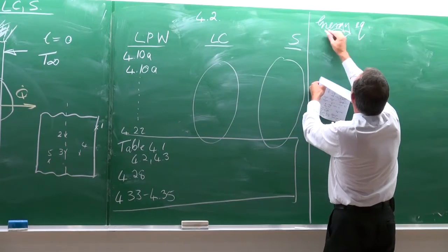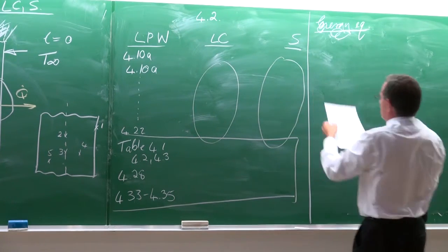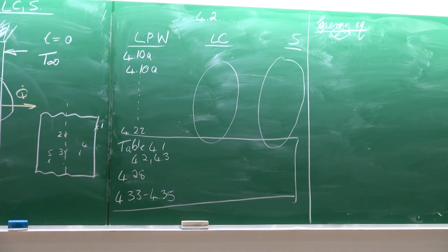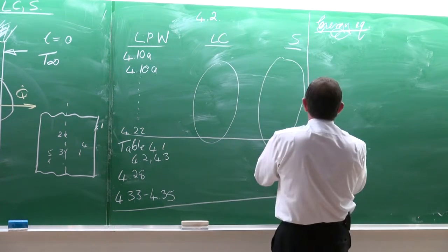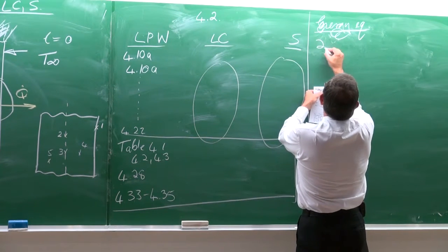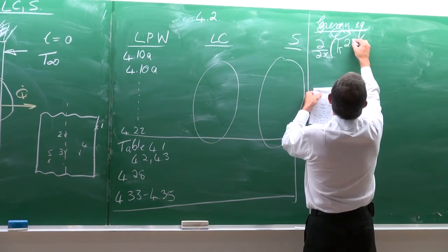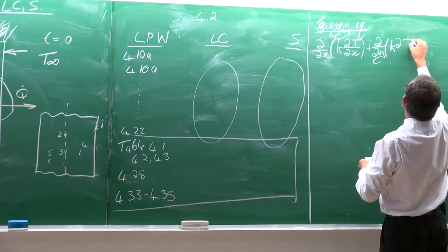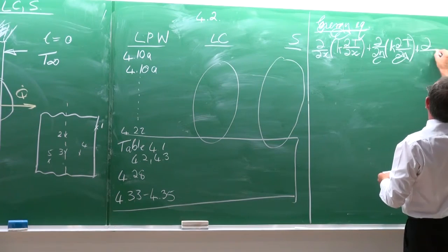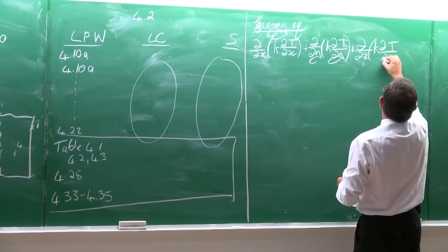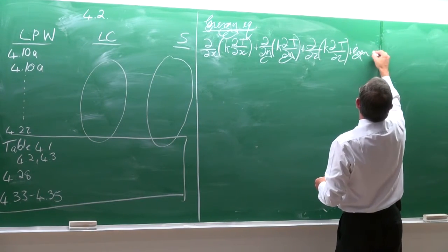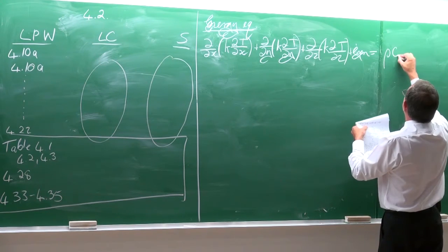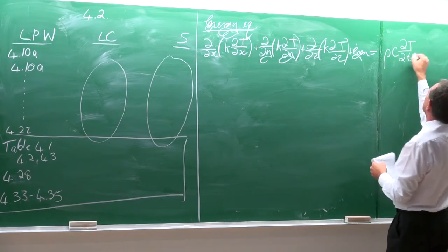The energy equation, almost in its most fundamental form relevant to us in heat transfer, which was derived previously in some of the previous chapters and in the previous module of this course, looks like this: partial d/dx of k dT/dx, plus partial d/dy of k dT/dy, plus partial d/dz of k dT/dz, plus E gen, is equal to rho c partial dT/dt. You recognize that equation?